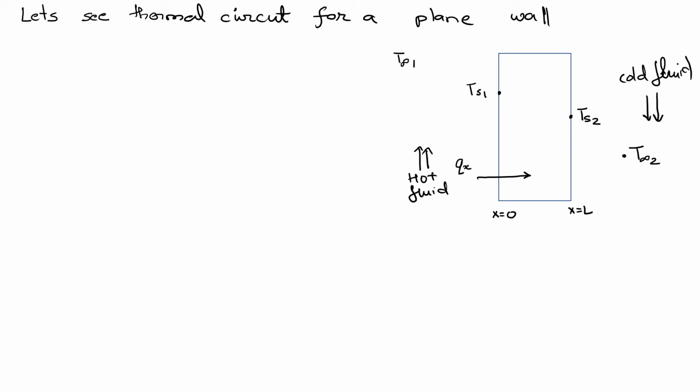So how will your temperature distributions look like? Your temperature distribution within the wall will be linear, so something like that. And you will have a temperature distribution looking something like this right here, and something like this between TS2 and T infinity 2.